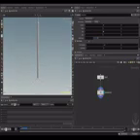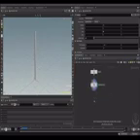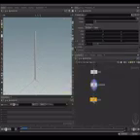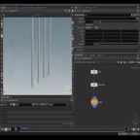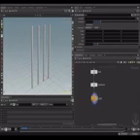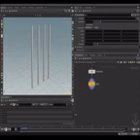And now I can set the uniform scale to 0.15. Remember, it's important to have a proper scale on your objects. Okay, so let's copy this box 4 times with a copy and transform node to the x-axis 4 times like this. And now the trick is to shrink the object in the directions we want the fractures, break it, and recover the original transform procedurally.